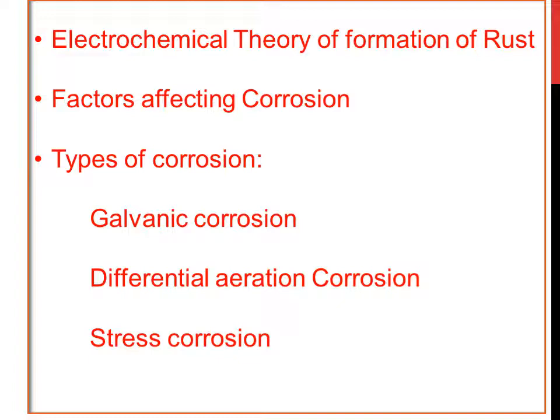So always it is observed that the lower the pH level, the corrosion rate increases, because as the pH decreases, more H plus ions are available, so that they undergo reduction and readily liberate hydrogen gas near the cathodic area. So the corrosion process takes place continuously.